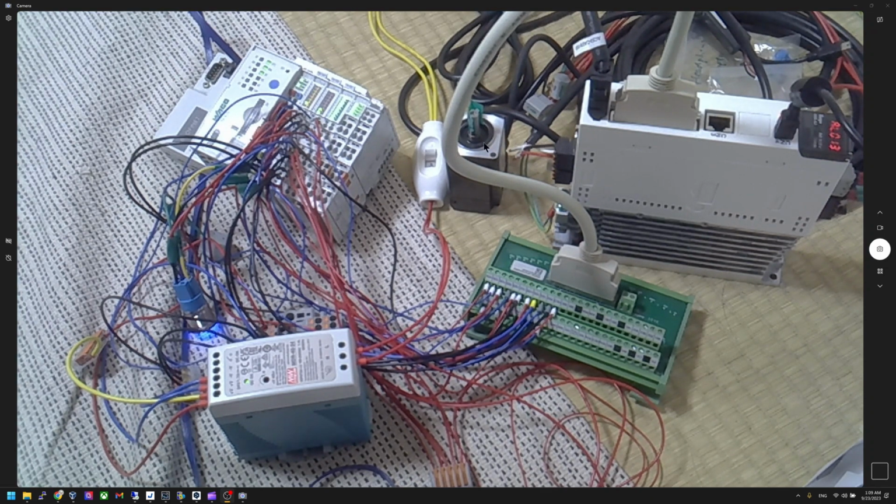And here's the servo motor exactly, and here I have a small switch to simulate an e-stop, and here's the lamp that will show you if there's any error of the servo drive. As you see now, it says A001V, it means that there's an alarm happening inside the drive, so that's also why this lamp is turning on.